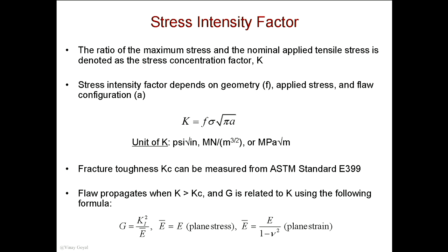Another measure of crack propagation is stress intensity factor. And so stress intensity factor is, in essence, if there's a crack in the structure, the stress at the crack tip will be infinite. Stress intensity factor provides you a means of measuring that stress intensity, basically looking at the field surrounding the crack tip.